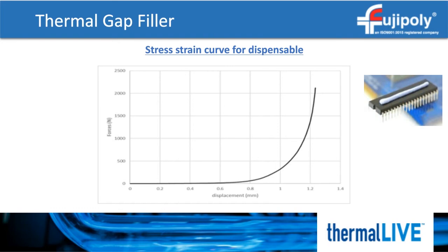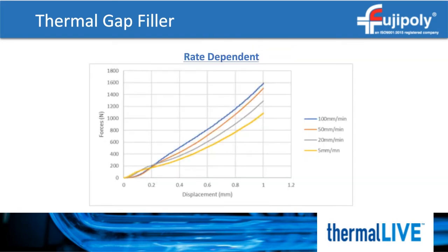Another characteristic of gap fillers is the compression rate dependency and the stress created. It is probably one of the most overlooked characteristics of a gap filler. There is a tendency to just focus on how much the pad is compressed and ignore the rate at which it is compressed. Quite often the compression rate is uncontrolled. Basically, gap fillers, both putties and viscoelastic pads, are highly dampened and will create different stresses based on the compression speed.